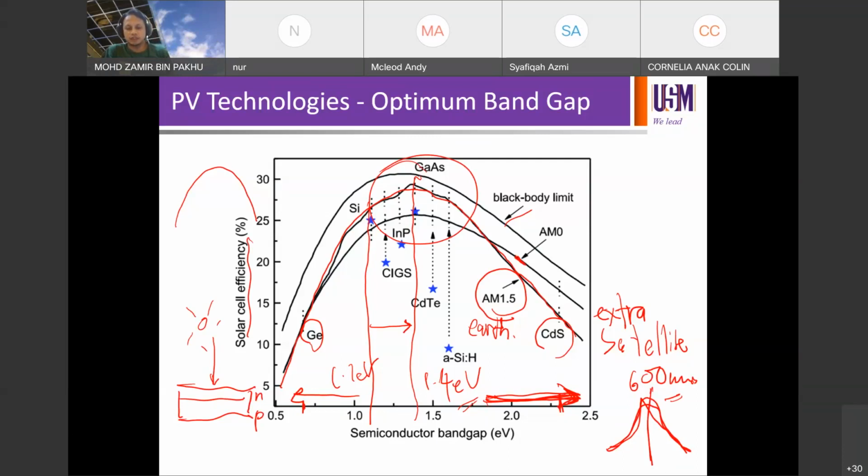If you use a band gap that is high, it's going to be more difficult, right? So let's revisit this equation. That's why I keep repeating EPH in comparison to EG. Remember, the light absorption will only take place below that. So you have the light absorption, then the generation, separation, and collection will follow. But you have to have the light absorption first. So that is the very first gate that you need to have in order to ensure solar cell operation.